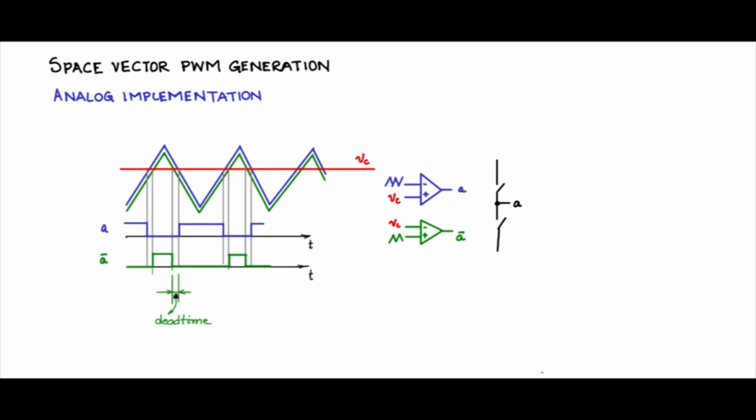You include the dead time in the analog case in this manner, by introducing a small offset between two carriers of the same frequency, whereas in the discrete case, you include this dead time by having a small low-bit count counter and introducing this dead time by adjusting the count value of that. This would in principle be the way it is implemented in analog.